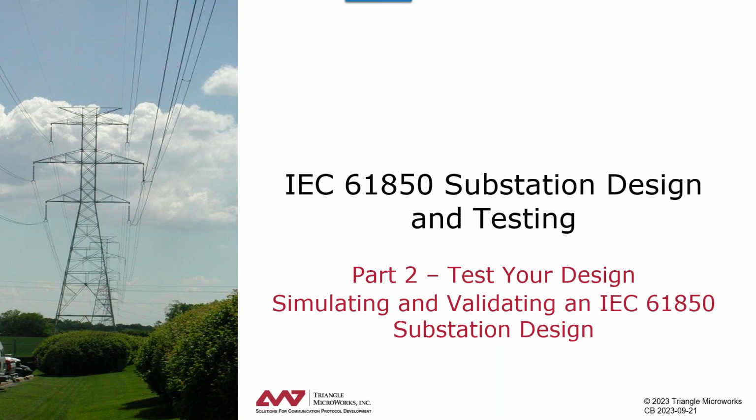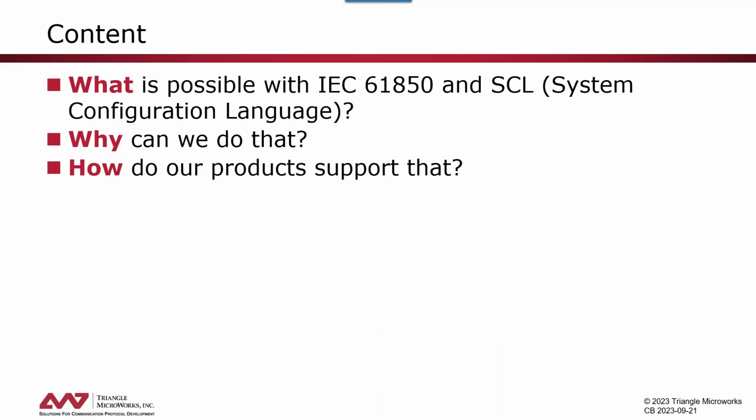So in the first part of this webinar series, Jackson had demonstrated how the design of a digital substation can be made using 61850 System Configuration Language, or SCL. In the second part, we will now show you how you can verify that the design works before you even need to configure the devices. With IEC 61850 and the SCL, the System Configuration Language, we have basic information that describes the system functionality in a machine processable format available. So let's have a look at that.